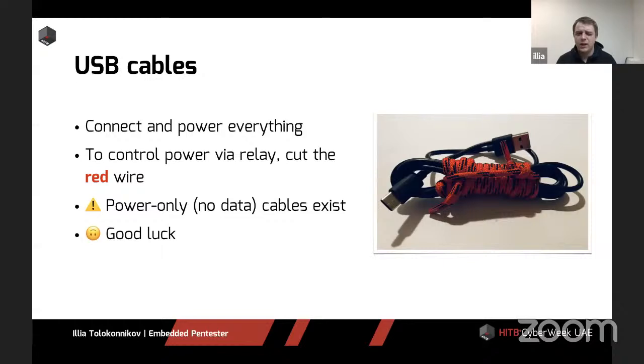Your biggest mistake when working with USB cables is treating power-only cables that don't have data lines as data cables that you want to route your serial connection through, for example. And sometimes they don't even come marked as power-only or with a data wire. So you kind of need to experiment. And we experimented with a lot of cables and found out that some branded cables did a really poor job, while some no-name cables did really well. Some of those were really good for power delivery, some really good for data. So when it comes to USB cables, good luck.